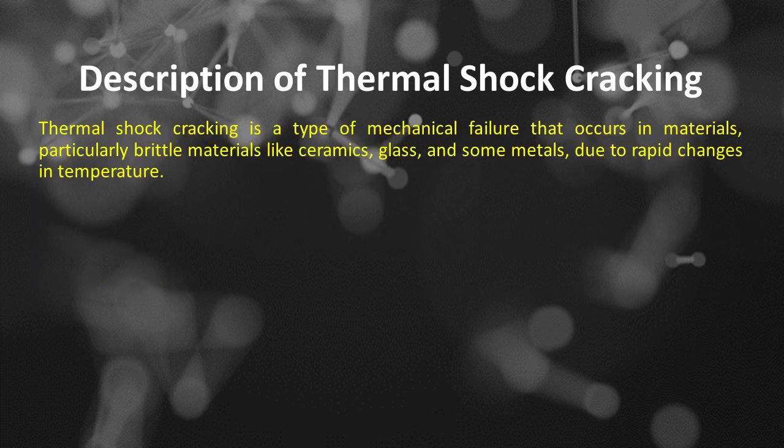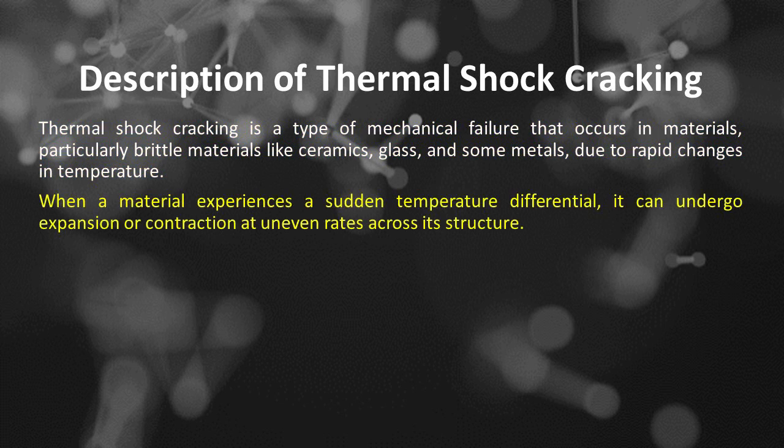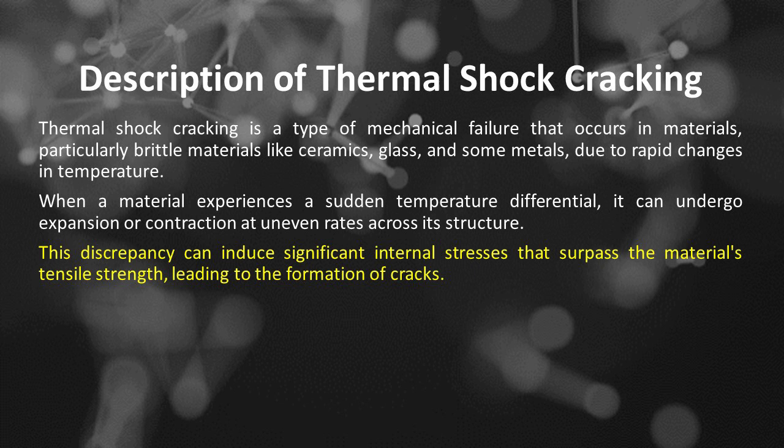Thermal shock cracking is a type of mechanical failure that occurs in materials, particularly brittle materials like ceramics, glass, and some metals, due to rapid changes in temperature. When a material experiences a sudden temperature differential, it can undergo expansion or contraction at uneven rates across its structure. This discrepancy can induce significant internal stresses that surpass the material's tensile strength, leading to the formation of cracks.